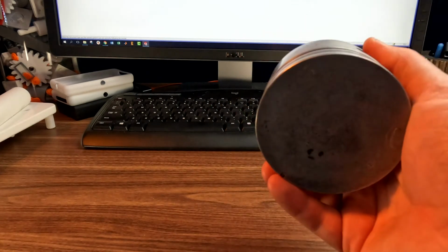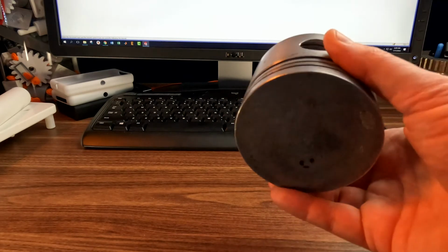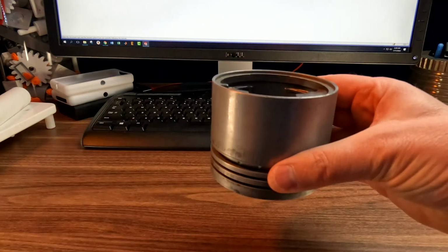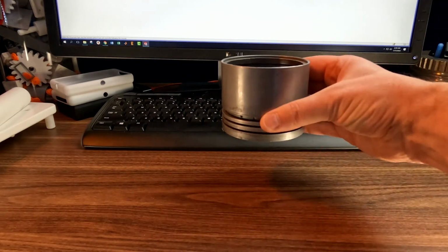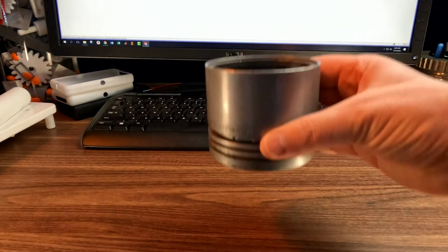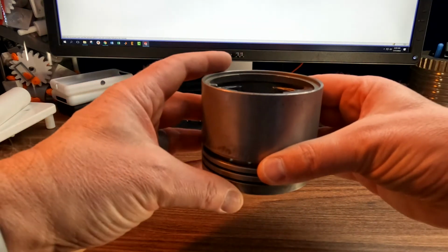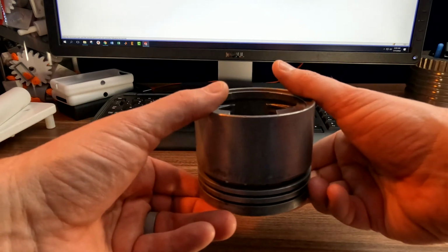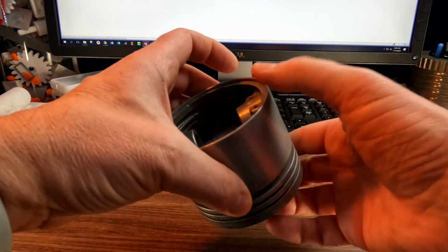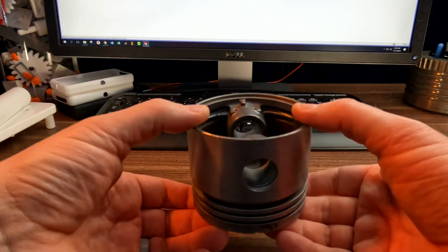This part, and every object, by the way, has 6 degrees of freedom associated with it. That is that the product can translate in the X direction, or in the Y direction, or in the Z direction. Those are 3 degrees of freedom. And then it can also rotate in the X direction. That's another degree of freedom. Or rotate in the Y direction. That's another degree of freedom. Or it can rotate in the Z direction. That's another degree of freedom. So there are 6 degrees of freedom.